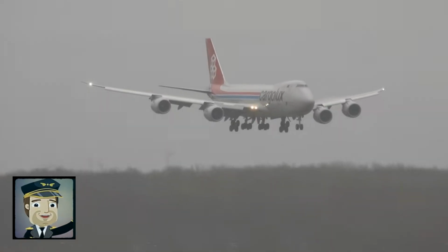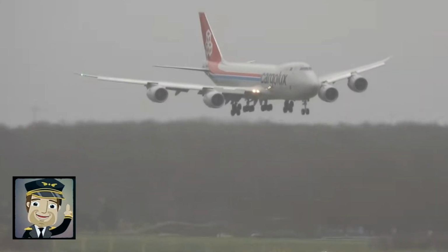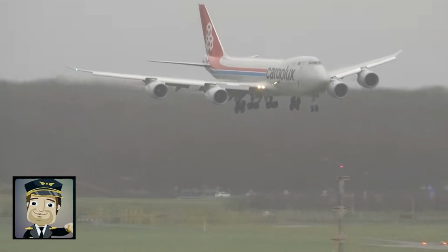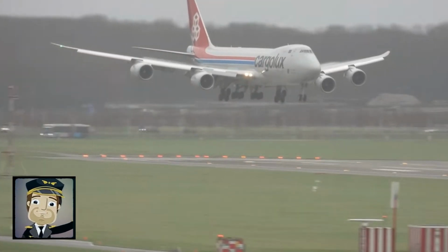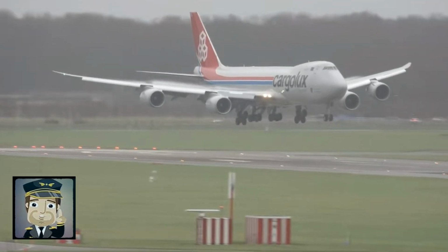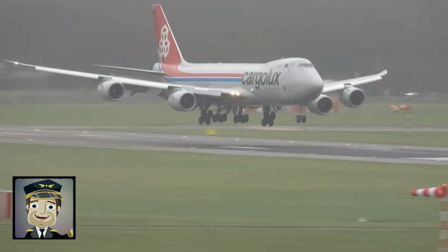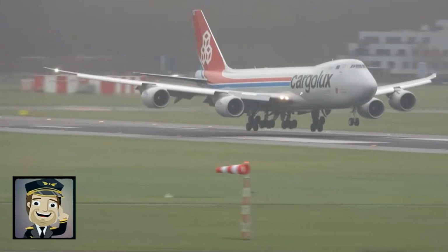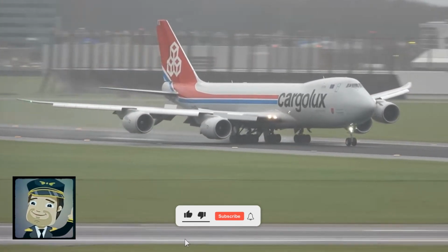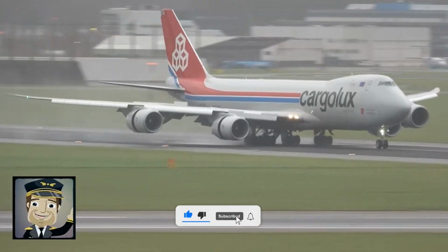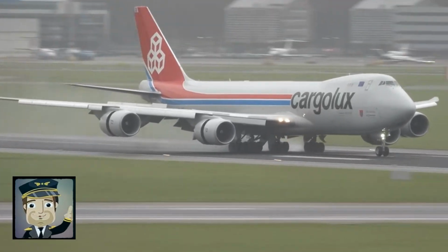This compensates for the lateral drift caused by the wind, allowing the aircraft to follow the runway's center line during approach. The greatest challenge of this technique lies at touchdown. The pilot must perform a smooth adjustment, called the de-crab, straightening the nose just before the wheels touch the ground. If this transition is not well executed, it risks excessive stress on the landing gear and loss of stability.